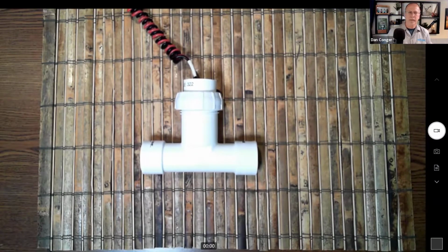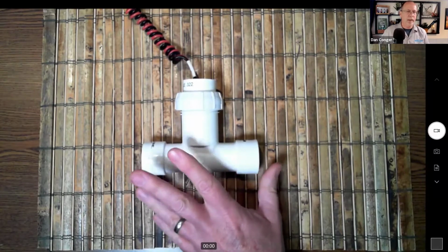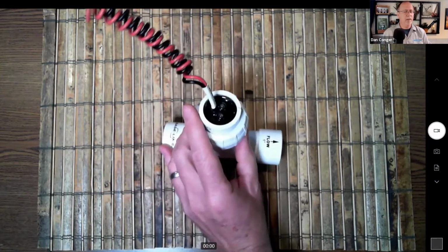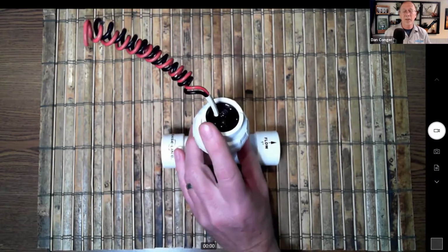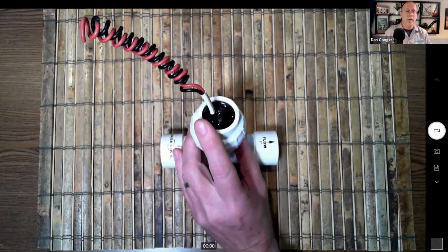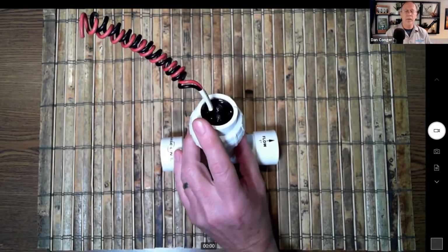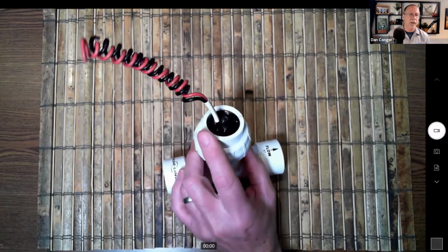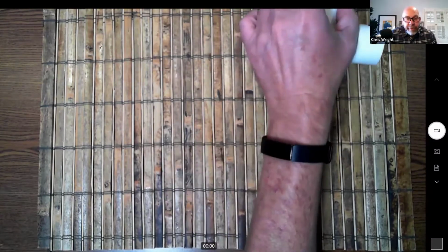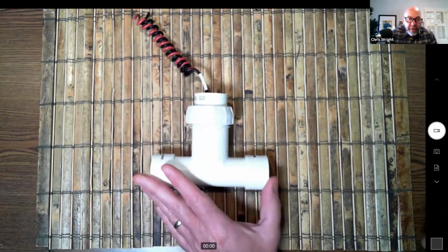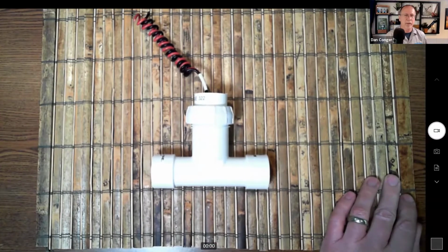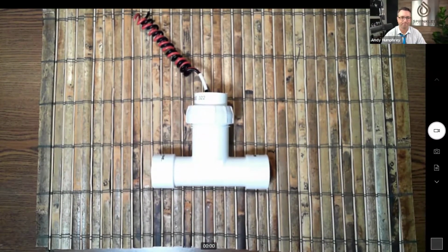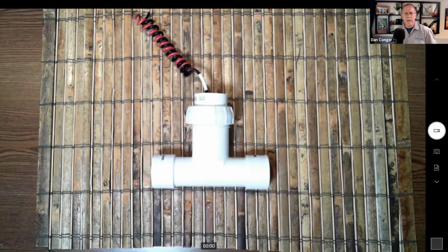Right. Okay. So as we get into the larger sizes, it'll be a saddle, but I think the same impeller works on all those, which is why that K value becomes really important, right? That K value is going to let the controller know what size pipe this is in, and it'll get those values appropriately. So is the K value for a 2-inch going to be different than the K value for a 1-inch? Absolutely different. Like a conversion factor, right? I think I've called it a translation or a conversion factor.